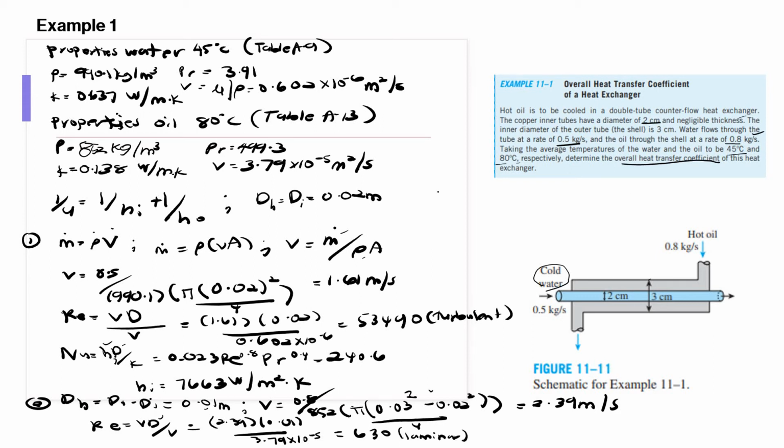Okay, I need to take this space to calculate the Nusselt number and also heat coefficient. So we have to assume that this flow inside the annular space is fully developed. So the Nusselt number that we need to consider is the Nusselt number on the tube side of the annular space, which is Nu i, inner Nusselt number.